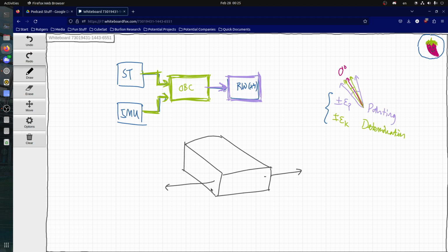I think the way we can try to get around that would be designing our experiments to be more inclined towards, okay, the Earth is here, do your experiments in this half of the sky. Always try to keep your star trackers pointed away from the Earth. If that doesn't work, we can always use IMU data to make up for a poor, not unusable, star tracker.